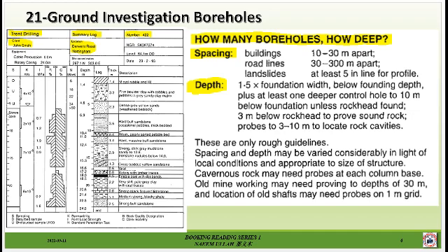In this slide you can see on the left side we have given a sample of a logging format. On the right side, how many boreholes, how deep. To investigate an area, how many boreholes you need to drill and how deep. Spacing. For buildings, 10 to 30 meters apart. Road lines, 30 to 300 meters apart. Landslides, at least 5 in line for profile.